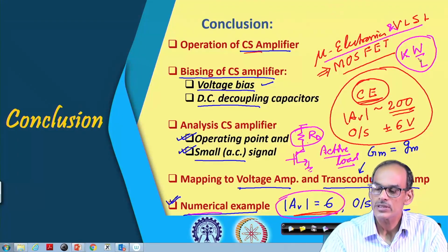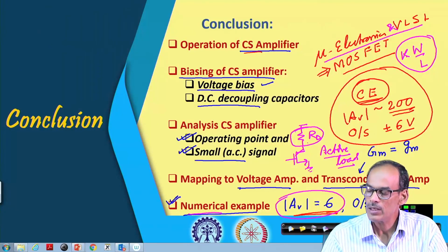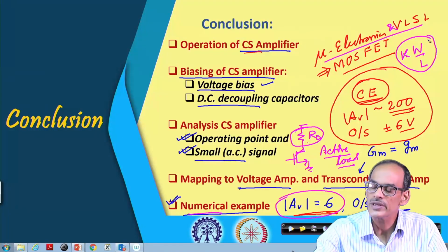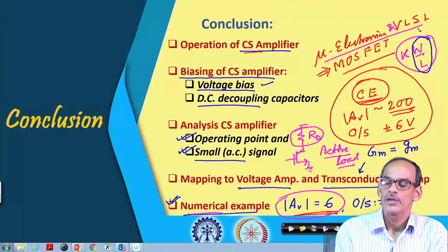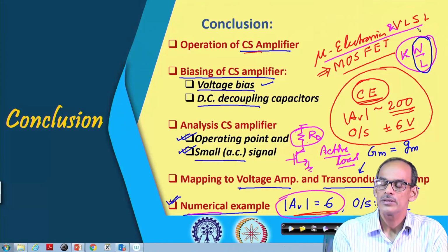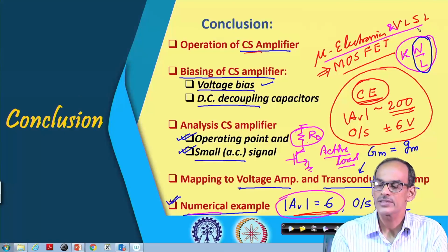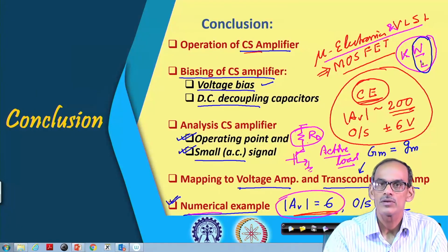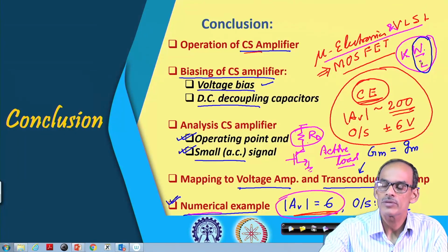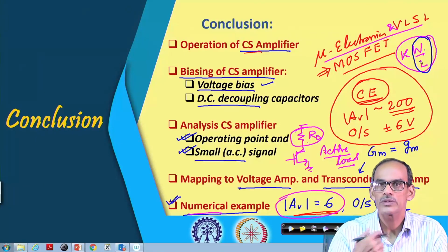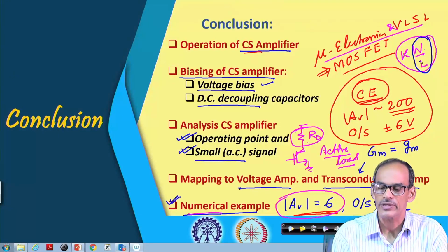But when you consider VLSI design, the additional flexibility is that the designer can decide what W and L will be. So, in analog VLSI design, W and L will not be given; rather, the designer has the freedom, and of course has to make a meaningful selection of W and L to further optimize the performance of the circuit.